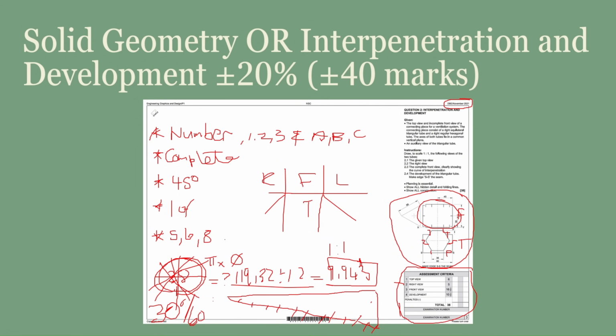And then you need to draw parallel lines from this line on all the points on your division line. So you'll draw it up until you touch the line, parallel to each other. And then this line will be divided into equally spaced parts. Also take note that you will always use auxiliary drawings to help you to get certain points on different views.